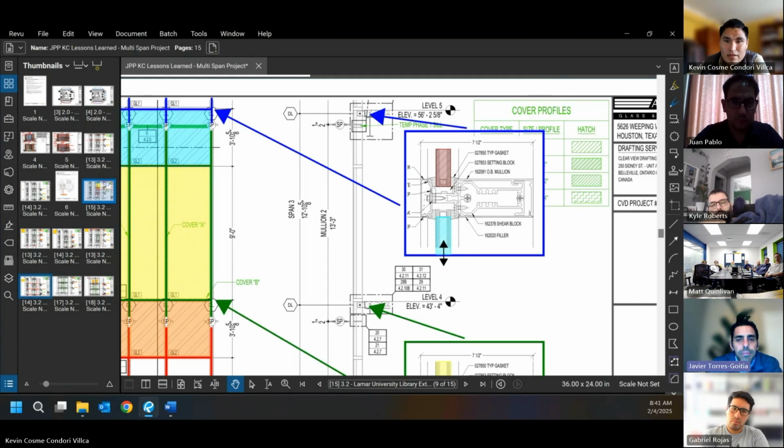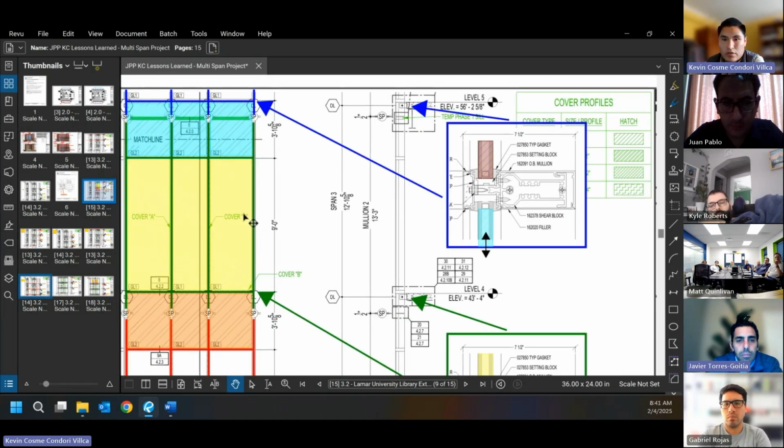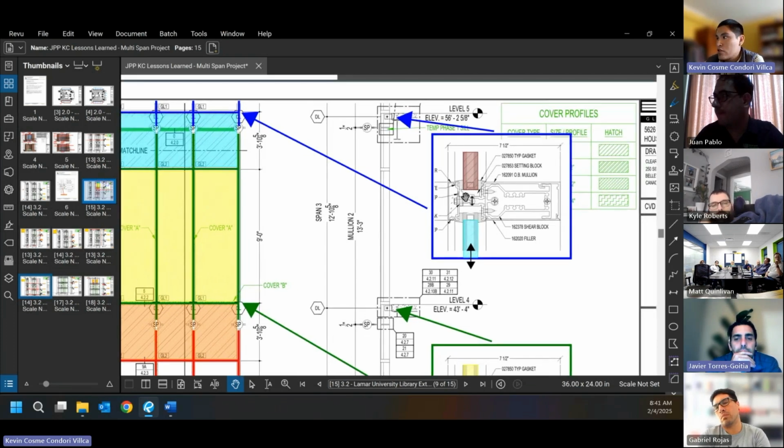And the glass marked in cyan would move downward, reducing the bite it has with the horizontal mullion. In this case, the glass would not actually fall out of place since it will still be supported by the vertical and the lower horizontal mullions. We would face the problem of water infiltration.